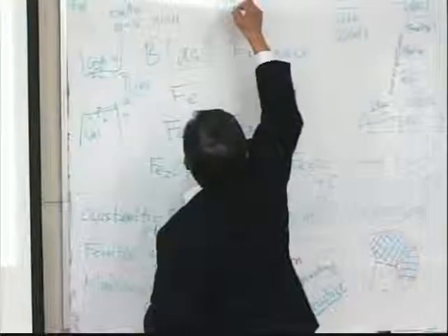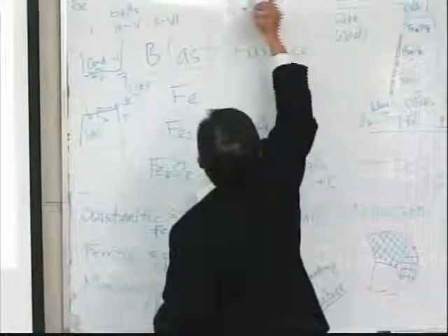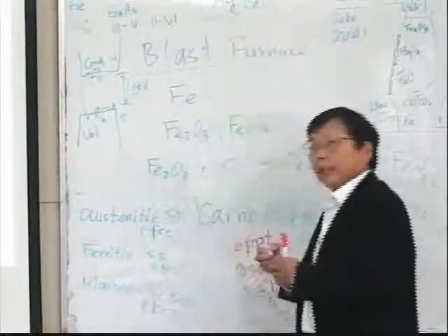We call that electrical contact material. Those are composite material, a silver matrix oxide composite. It actually is cadmium oxide, CdO. It is silver with CdO put together.